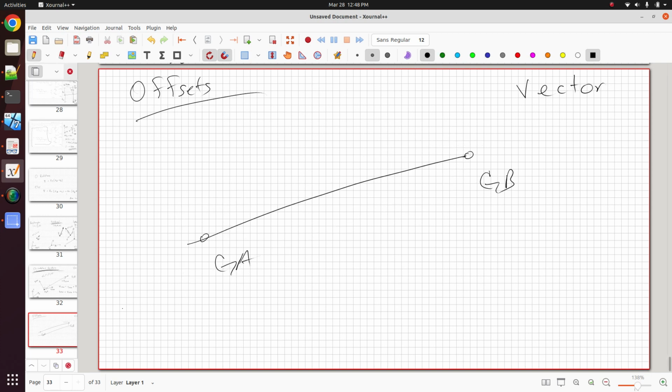Let's suppose that here at the top right, this is x and this is y for the basic coordinate system, which has an ID of 0, and an out of plane would be z. Let's suppose that you want to offset the shear center as an example. So the shear center might be offset like this. Suppose you want to offset it by -1 and then +1. So the offset would have this vector, -1, +1, 0.